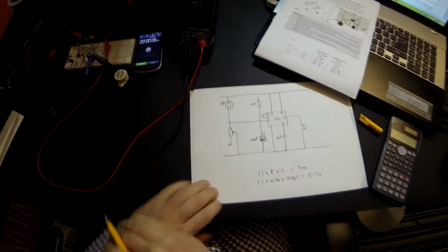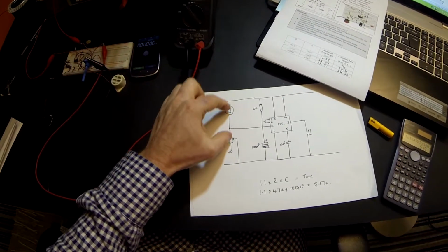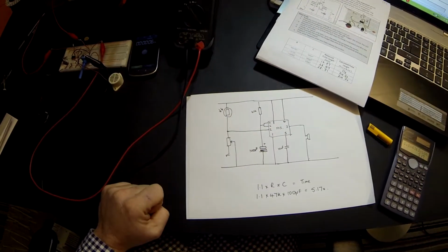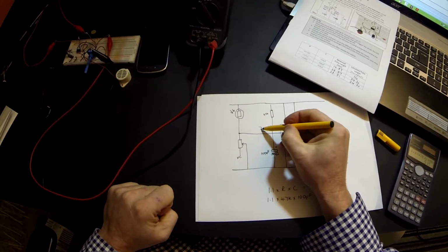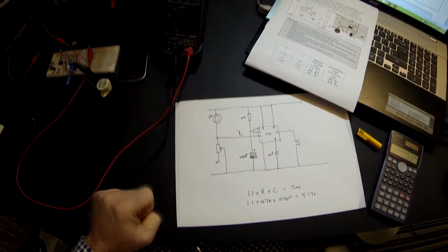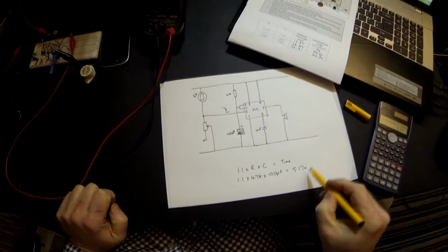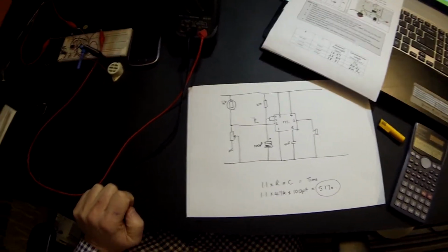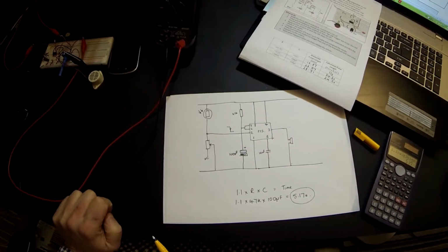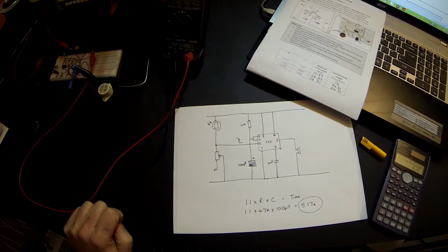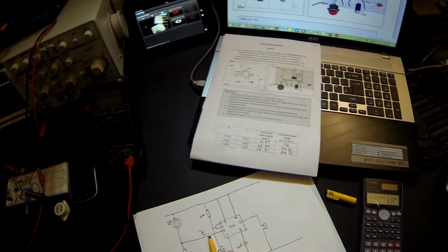And that's my circuit symbol for a buzzer. So I have a complete circuit diagram where I have my light circuit, which is triggering my monostable. So the low is going in, and we can indicate that by showing going from high to low. We have our resistor of 47k, our capacitor of 100 microfarads, giving us a 5.17 second delay. And the output remains high for 5.17 seconds, turning on our buzzer. After that, it goes off. Job done. This is the end of tutorial 14.